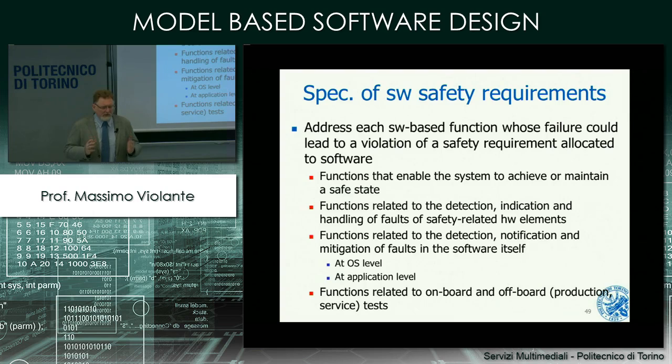So these are all checks that you can do in your software to deal with possible failures that could happen due to faults affecting the internals of the system or the elements that interact with the system. All of these are mechanisms that you have to specify here. Then, once the fault is detected, you will have to notify somebody else of the detection of the fault, so that the function that triggers the reconfiguration for entering the safe state is activated. And this has to be done here.